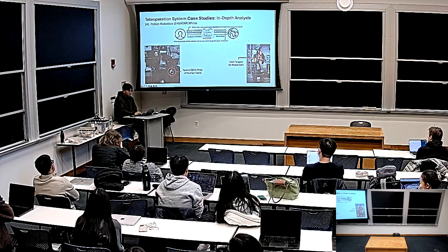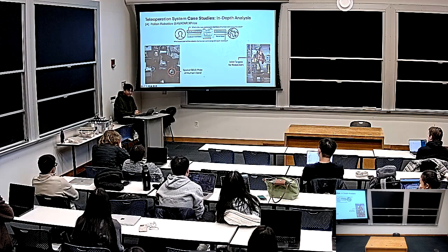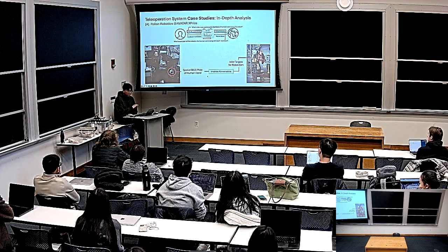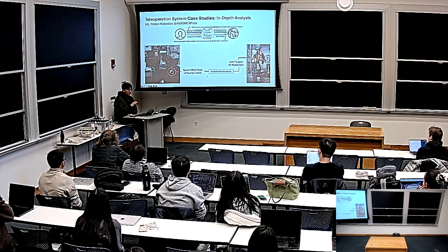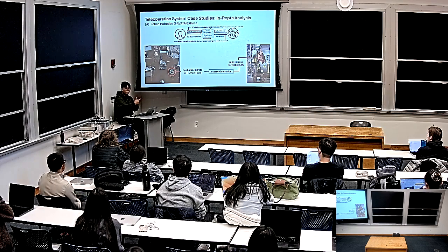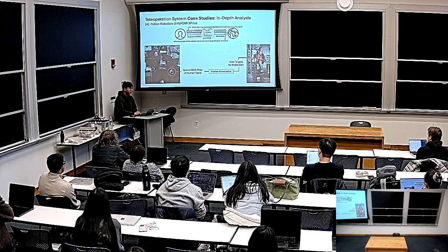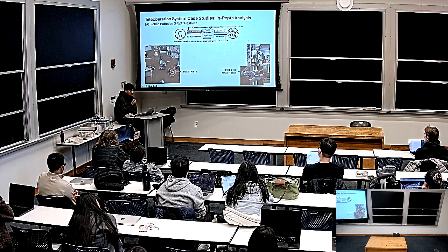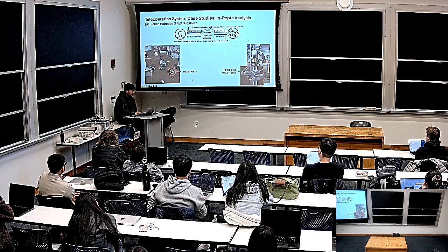So what should be the action converter over there? Have a clue? Something called inverse kinematics. Inverse kinematics converts the target pose of the end effector to the actual joint angles of the robot arm, for each joint. And this controller also controls some other part of the robot, which is also the hand, right?